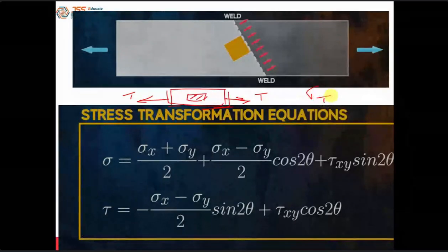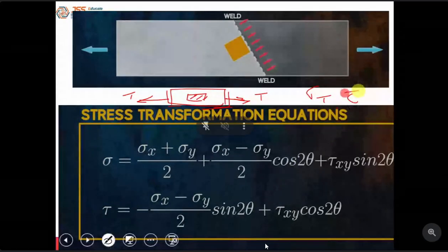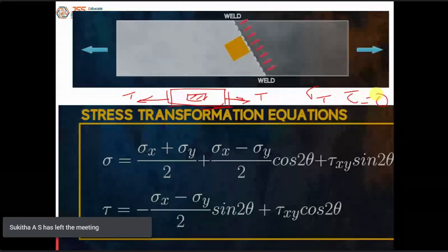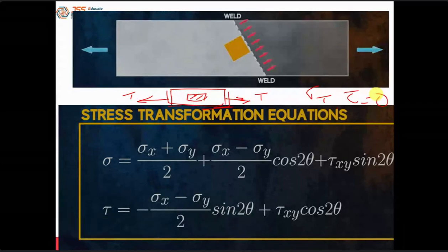Tensile stress. Is there any shear stress developed? No, because the load is not acting in the tangential direction. Okay, this is the first case. Those who are not getting this point, watch video number 1 of strength of material. Everything is covered, and I have covered what principal stress means there. Okay, now things are clear. Only normal stress is developed, no other stress like shear stress.